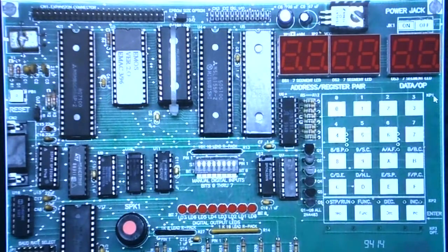So I thought we'd do a review using the Primer Trainer simulator. So we turn on the Primer Trainer and we come up with FF01, and the contents of that memory location is 00. Now they want us to enter a program into memory. So at FF01 they want us to enter DB, and we have to press the increment to enter the data into that memory location. So if we press the decrement key, we can see at FF01 we have stored DB.